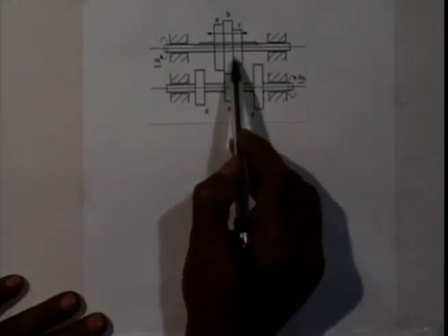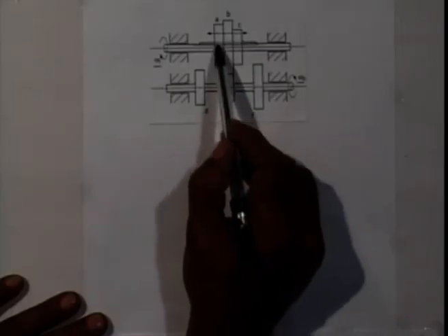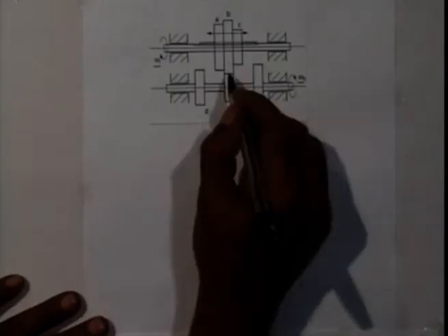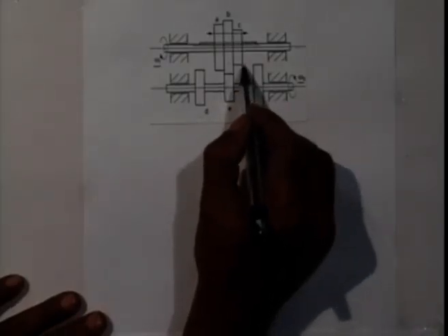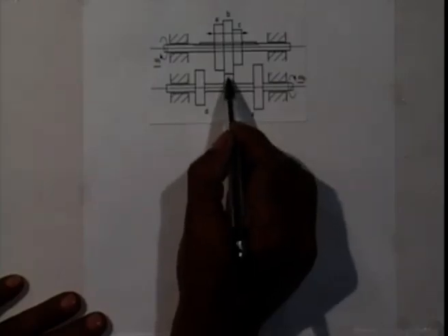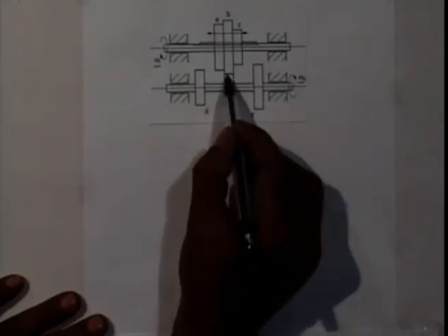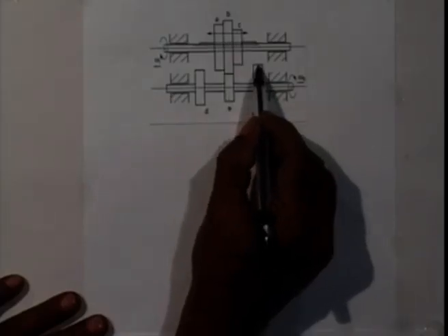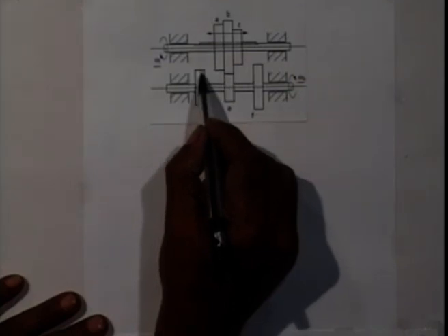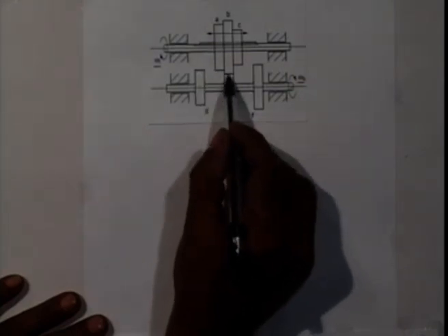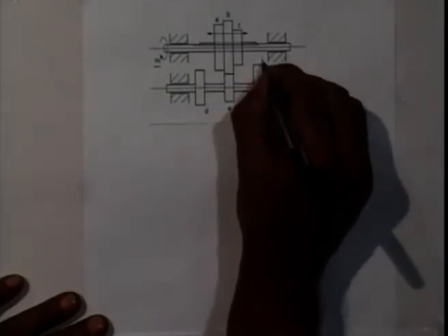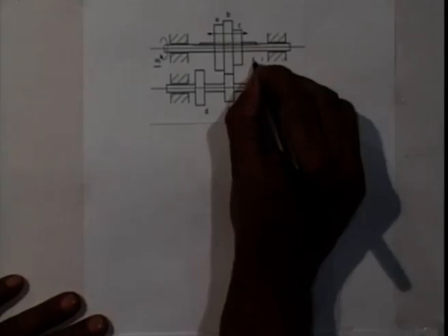This is one rigid body, but the number of teeth are different on these 3 gear bodies A, B and C. The thing to note is that before this gear comes in engagement with this gear, the gear which was already in engagement must be totally clear. It must leave this engagement before it starts engagement. Similarly, when I move it this way, before this gear comes in engagement with this gear, this engagement must be fully clear.